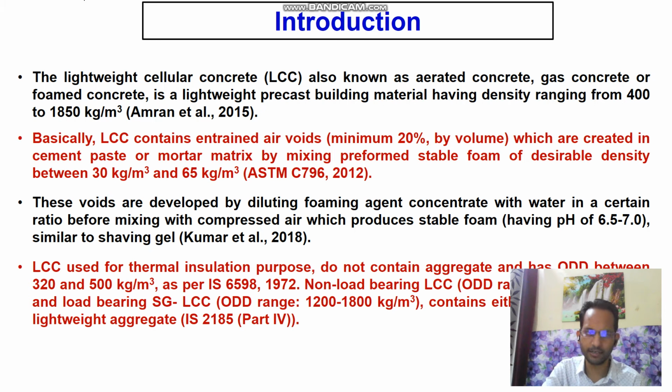These voids are entrained by diluting the foaming agent, or you can say surfactant, with water in a certain ratio ranging from 1:20 to 1:30 or 1:40, 1:50. One can use it as per the quality and quantity of the foaming agent, and the temperature also plays an important role. I will discuss how temperature plays an important role during the development of the preformed foam.